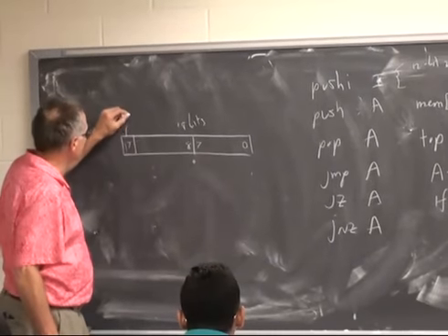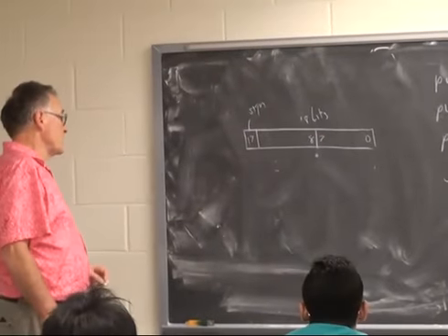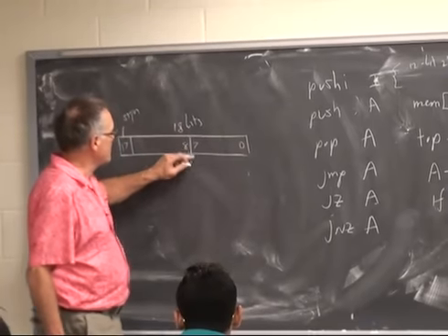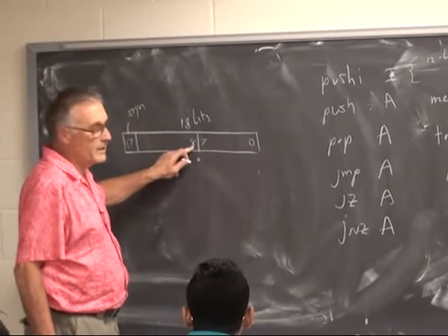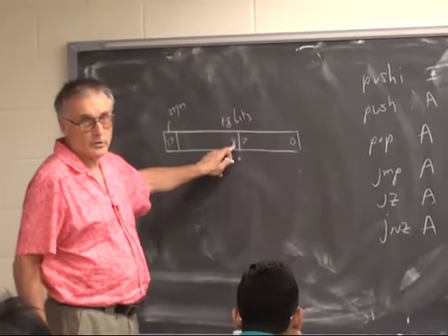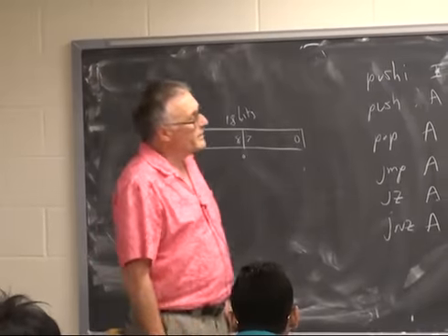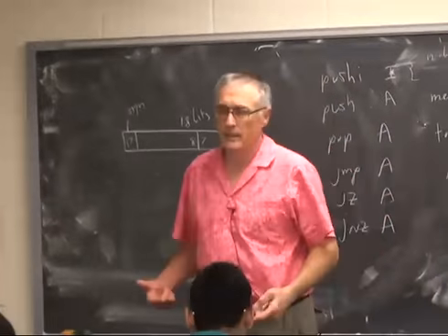And this is the sign bit. Bit 17 is the sign bit, 18 bits total. Bit 7 is the highest order fraction. Bit 8 is the lowest order integer bit. So the multiply takes two 10.8 numbers and returns a 10.8 number.